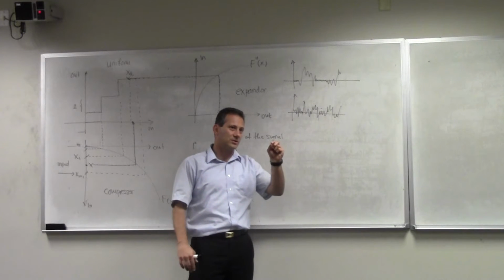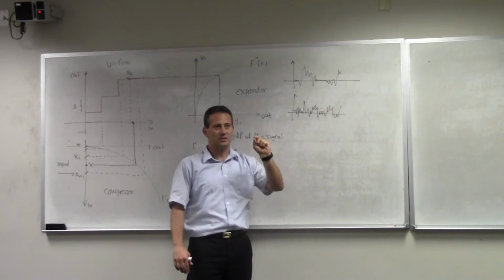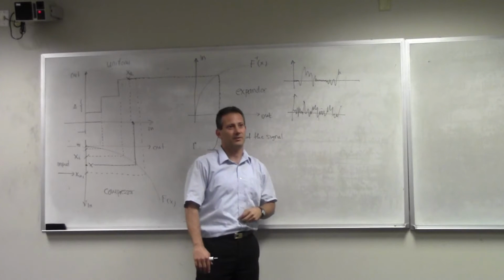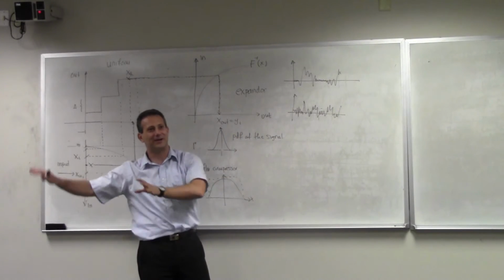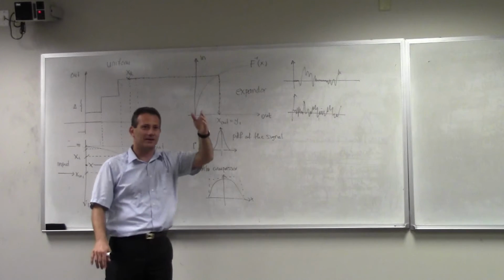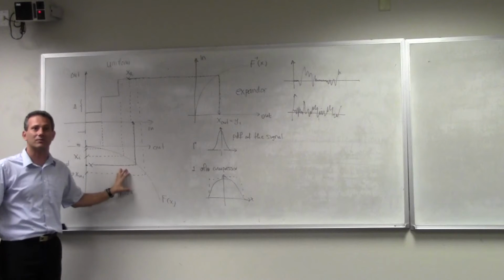So a lot of compressors come with a gate threshold that allows you to say that if the signal is below this threshold, then gate it out. But we're going into guitar tricks now. That's why it's called compression, because it compresses the dynamic range of the power of your signal.